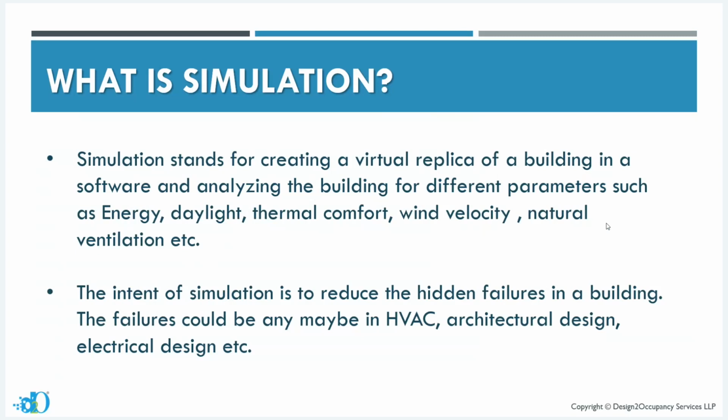So basically, what is simulation? Simulation is creating a virtual replica of a building in a software, analyzing the building for different parameters. So basically, what we are doing in simulation is we are making a virtual building, and we are optimizing the building with different input parameters. Like if we talk about the envelope, basically we have roof, glazing, walls, HVAC, then we have the lights. All these parameters we give as inputs in the software, and then we check and optimize the system for energy efficiency. So simulation is a very broad subject.